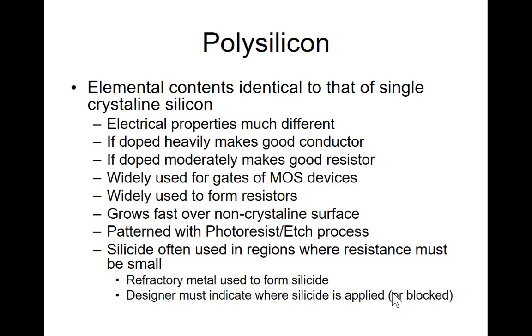And I don't know whether there is a high resistance poly in the 0.18 or not. In the 0.13, many students use the 0.13 process at GlobalFoundries, and there you have the high resistive poly. Last time we mentioned the HP, the high resistive poly, and that property can be very different.